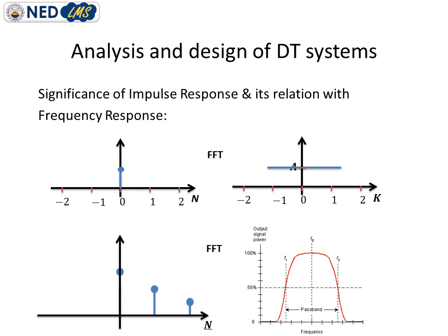Recall the concept we have studied earlier, that the impulse in the time domain is actually a constant line in the frequency domain. We also discussed this concept in great detail, that when we apply an impulse to any system, it actually means we are applying all the possible range of frequencies to that system. So from that we learn the behavior of the system at all the possible frequencies.